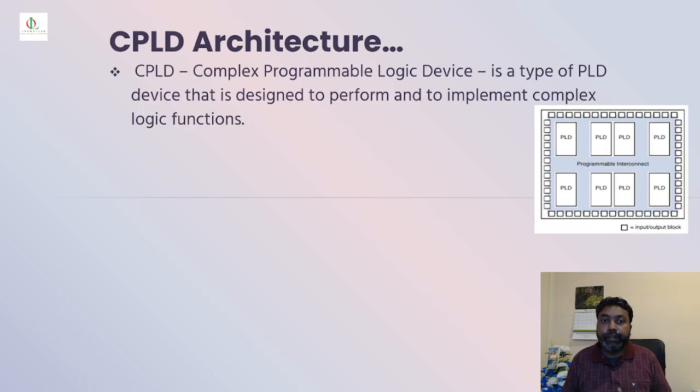For example, in microcontrollers, due to the limitations of the pins, the 8051 comes as a 40-pin IC and has limited pin usage, allowing only 2 UARTs. Whereas if you use a CPLD, you can almost configure every pin to be used as a UART. And if you want to use 10 UARTs, yes, you can. CPLD is specifically designed for that, to implement complex logic functions in the form of input-output peripherals.